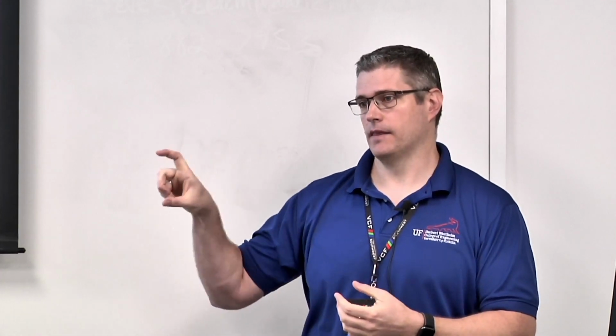Follow up on that. With add immediate, how many microcode rows does that have to execute to completion? For an add, I would imagine a 4-cycle clock, like 4 microcode rows to finish. Okay, just 1 microcode. Yeah, for add immediate, it would be 1. For add extended, it would go into a micro op that is just for extended memory addressing, and then go to the second micro op to do the add.